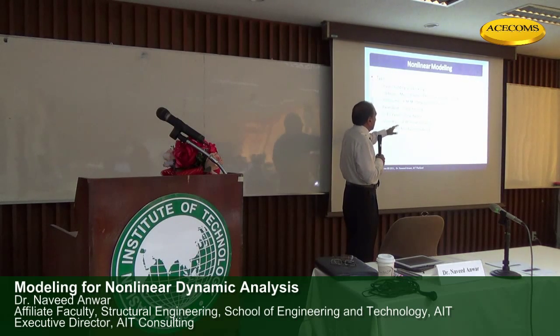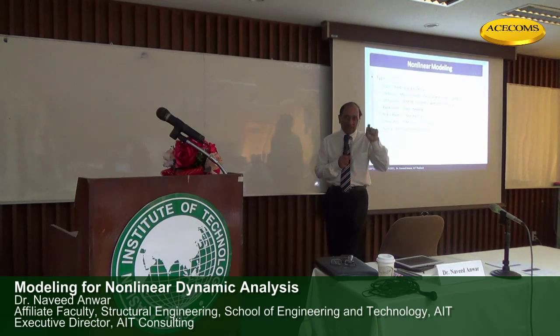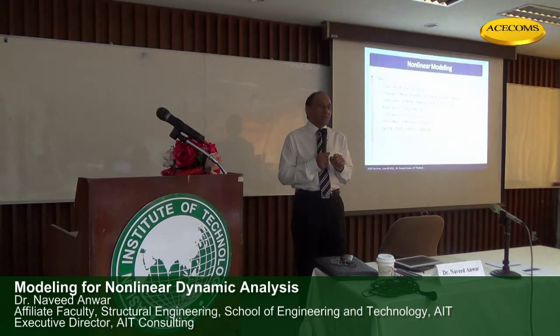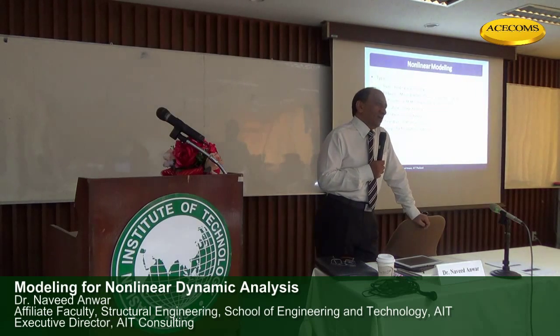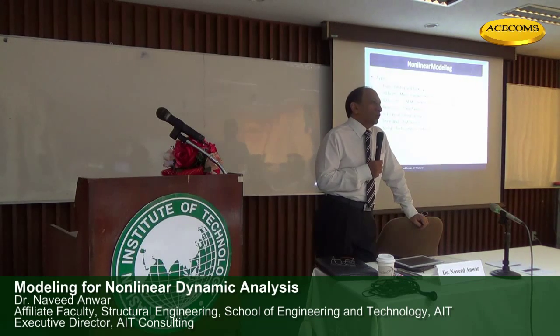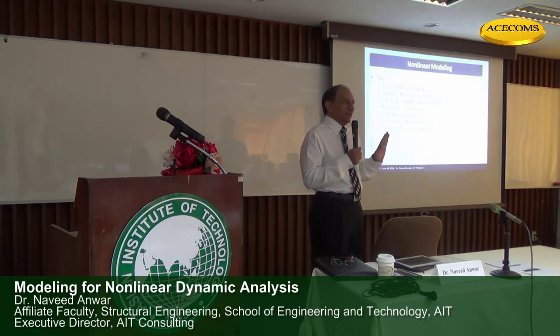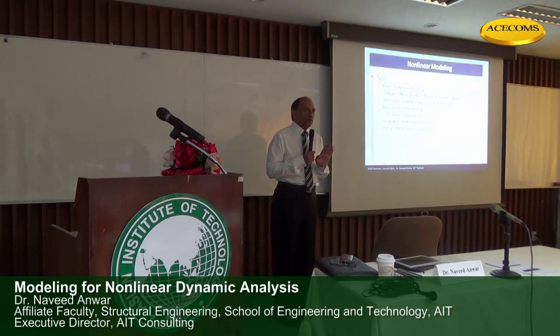Shear wall: PM and shear interaction, which we normally cannot do. I put an exclamation mark in front of that. It is still something that is really lacking in our tools. Another shortcoming right now is that all of our design and analysis tools do not consider interaction between flexural and shear. They consider them to be independent in a shear wall, but they are not. So that's another shortcoming that we all know.